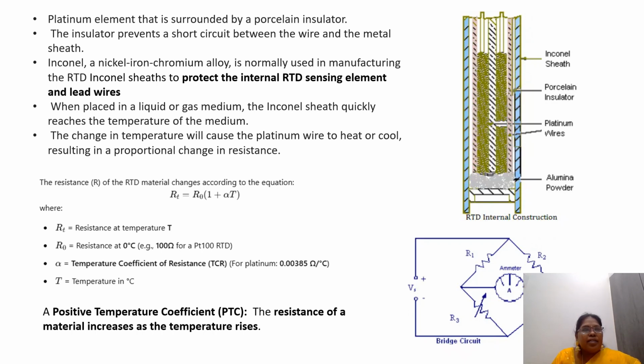This RTD is called a positive temperature coefficient device, because as the temperature increases the resistance value also increases. If the temperature increases and the resistance value decreases, then we call it a negative temperature coefficient.